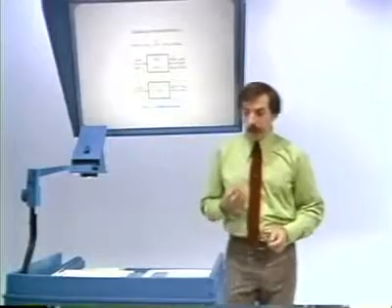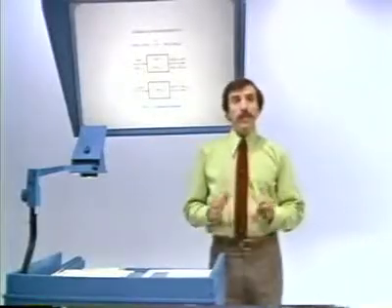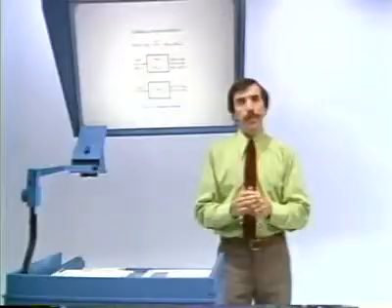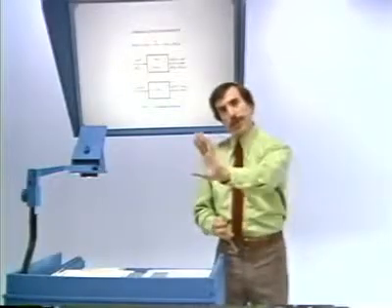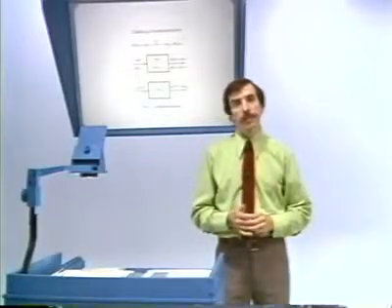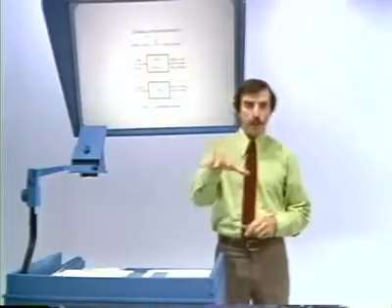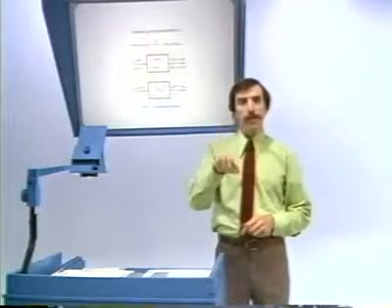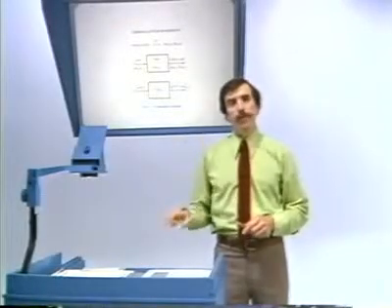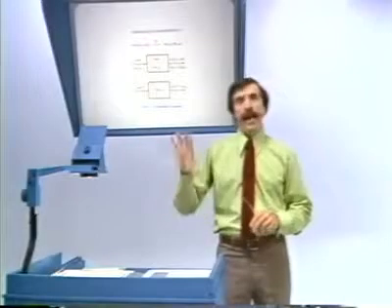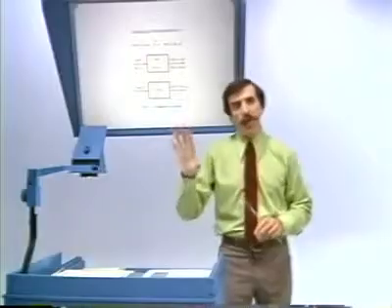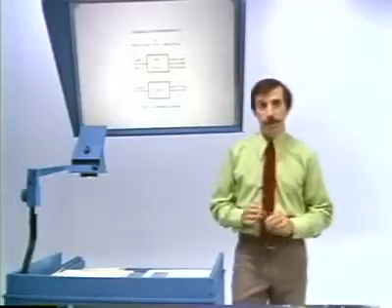So, in fact, the convolution property simply is telling us that in terms of a decomposition of the signal in terms of complex exponentials, as we push that signal through a linear time invariant system, we're separately modifying, multiplying by the frequency response, the amplitudes of the exponential components used to build the input, and that sum in turn is the decomposition of the output in terms of complex exponentials.